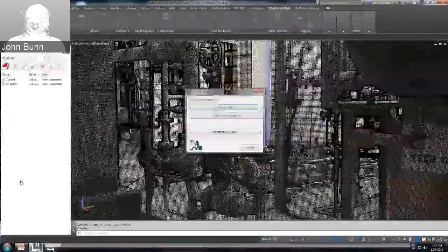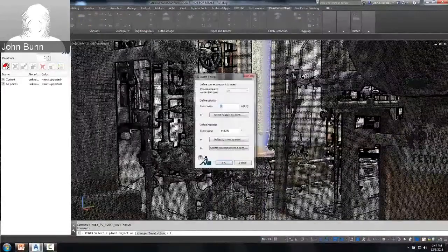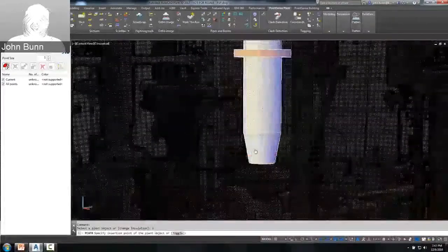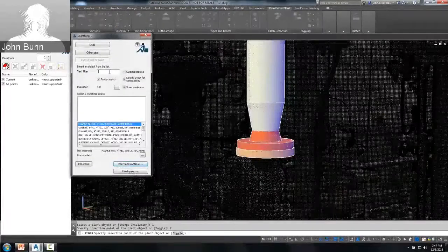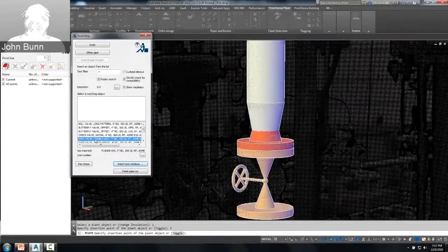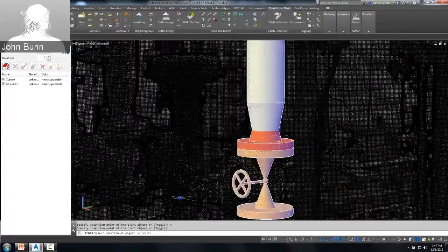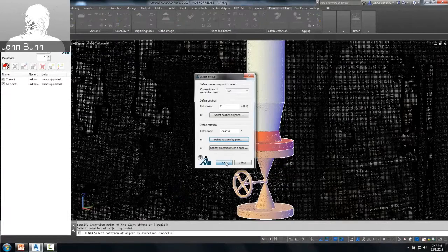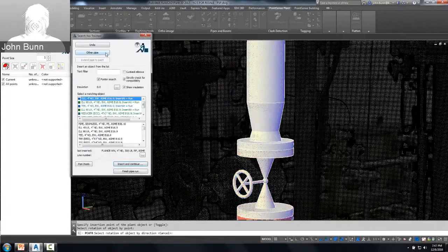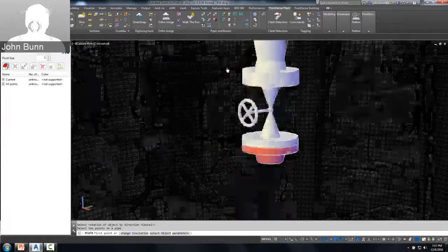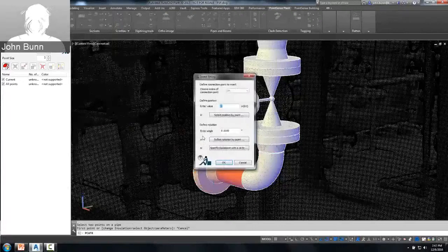We've got a pipe with a reducer coming down. I'm just going to continue from that reducer and choose the flange here. And again, this is just a generic flange, but it looks like a flange. The only thing that we're missing really is the bolt pattern or the bolts, but that's normal. So same thing here with the valves. You can see here, even a generic valve now has a hand wheel. If you were to import these from Plant 3D, however, you will get a hand wheel length or a stem length that matches what is defined in that catalog or in that spec. But I just wanted to show here that you can definitely see it's a much cleaner look. And again, this is just for generic fittings.